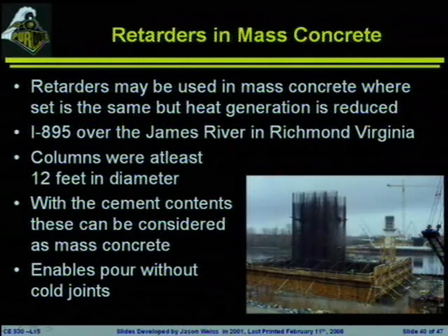Other places where you're going to see retarders being used, you'll see retarders being used in mass concreting applications. Now one of the things that I will point out here is mass concrete can mean very different things to different people. If you read your textbook or you read a lot of the ACI literature, they talk about mass concrete, and the one thing that everybody knows that's mass concrete is dams. All right, so everybody gets excited, mass concrete dams.